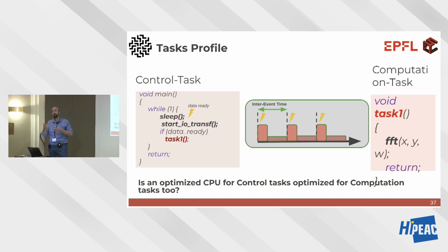So what do I do? Or maybe there are technologies that are not consuming a lot of leakage power. So if you do power gating, you save 1%. Very little. So it's not always a solution that you can go for. You can go for power gating only if the thing you are power gating is big relative to whatever you are doing. If it's the whole chip, what are you power gating? So if I'm on, I cannot power gate. What am I doing when I'm sleeping? I'm consuming? Leakage power, yes, leakage current.